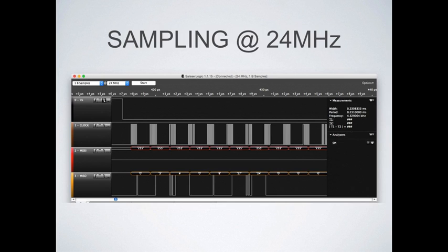If you take a look at it, it's the data on the master out, slave in. I'm most interested in that because there's some data coming from the master to the slave. My master is the microcontroller, my slave is the CC3100, and my microcontroller is configuring the AP, and somewhere along the way it's transferring the key.